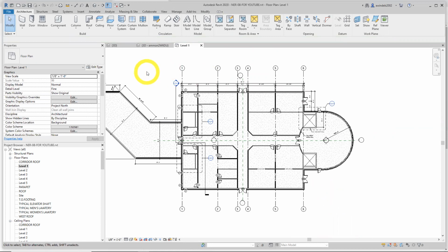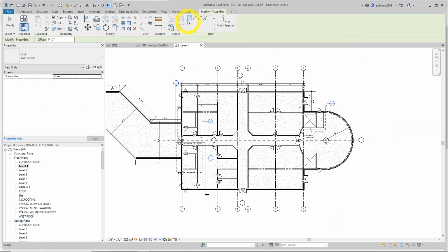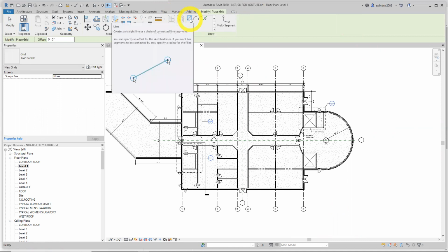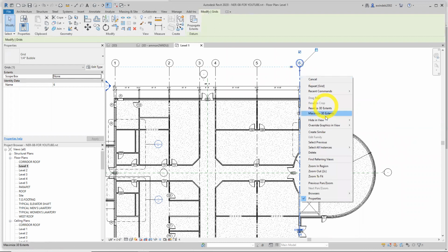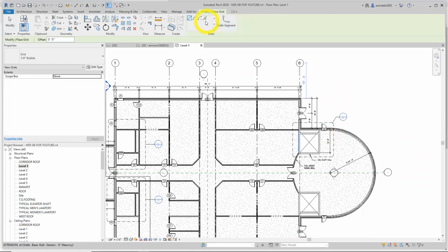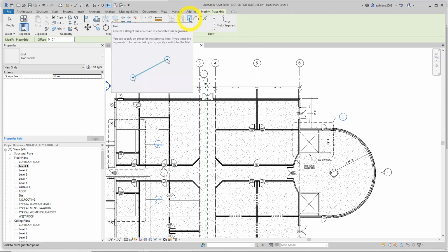We still have the grid. We don't. You could have kept it running, but we'll do another one with 2 lines. This one, or you could click on grid 6, for example, and say create similar. Either way, and we're going to have the line command open.